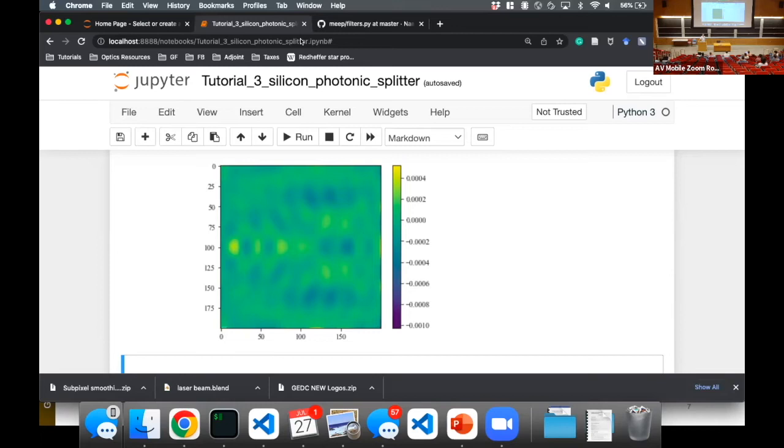I find that if you do it before the projection function, you lower the risk of getting weird averaging after the fact. In theory, if you optimize using perfect symmetry conditions, you should never get weird averaging, but nothing in the code is perfect and you always get some weird things. So I like to keep it safe by putting my mirror conditions before my projection rather than after my projection. Yeah, great question, Arjun. Any other questions at this point?